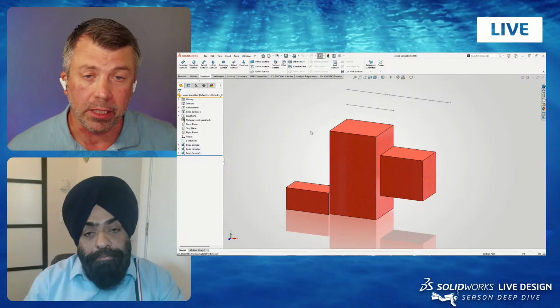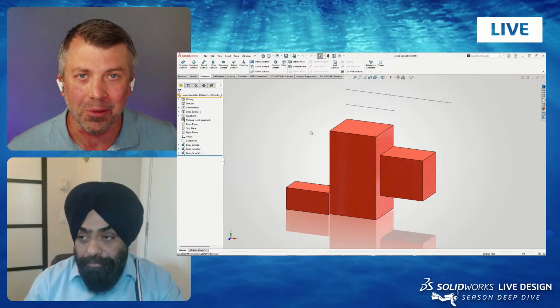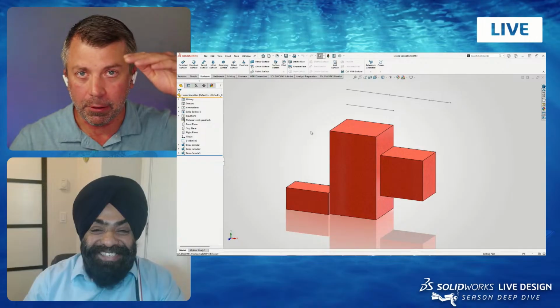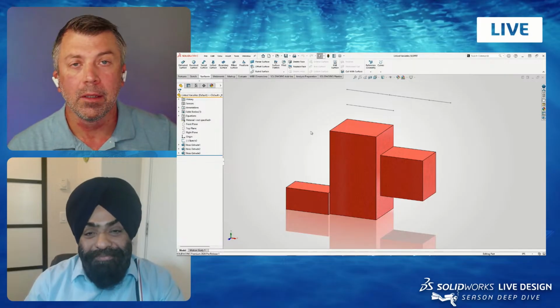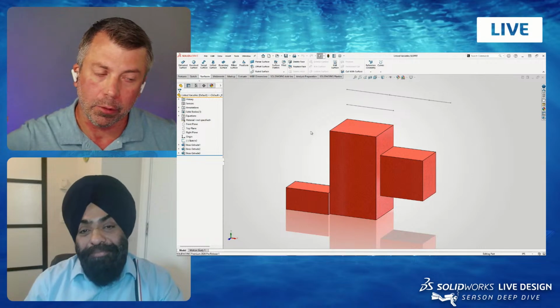Any application engineer, anyone new to SolidWorks, or someone showing someone else SolidWorks, what do we usually make? Plate with a hole, right? Yeah. So you start with a simple plate, a simple rectangle, give two global dimensions, build that equation to say, hey, if the width changes, change the height, add a hole. And then you can say, hey, let's have this hole driven by, again, an equation.